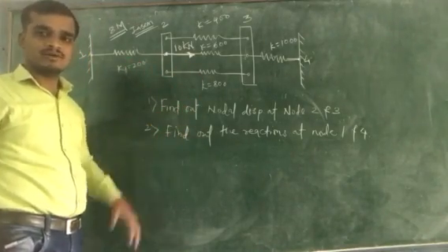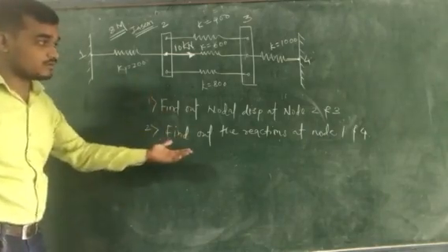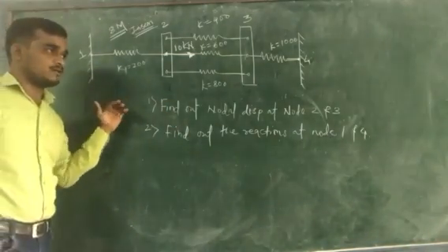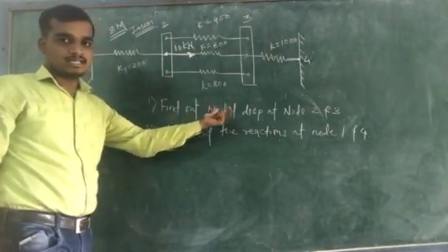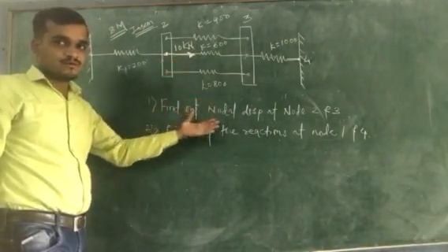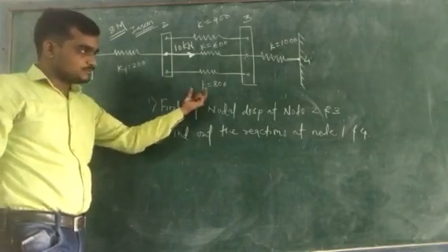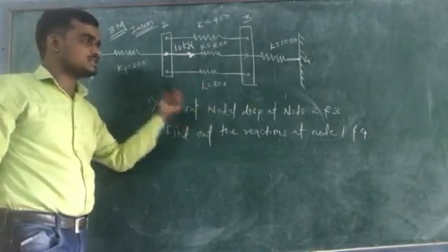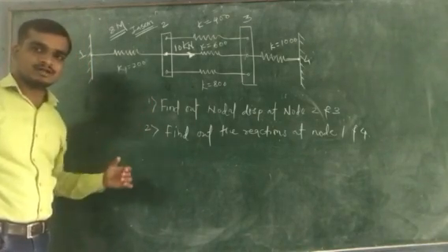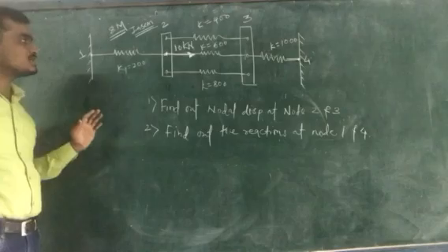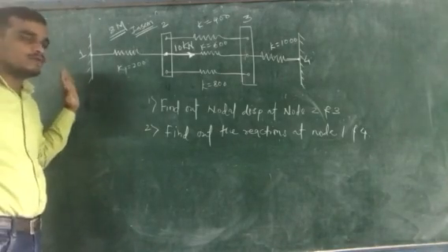Then next, you need to write down this global stiffness matrix into your force and displacement relationship. As there are 4 nodes, by using this global stiffness matrix you will get 4 equations. Then the next step is to apply the boundary conditions. First you need to apply the boundary conditions for nodal forces.